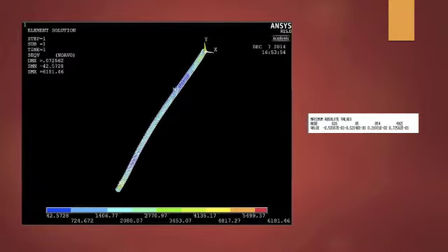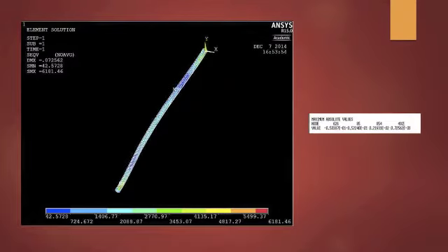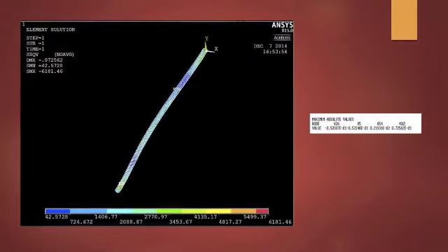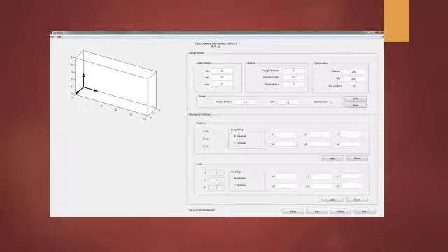One of the biggest issues of optimizing this beam is that it has a very big aspect ratio, since the diameter of the beam is so much smaller than its length. So we have issues of finding the right resolution and number of elements so that we can use the topology optimization. We downloaded software that allows us to change the number of elements used in the X, Y, and Z directions. We ran the topology optimization using a reduced aspect ratio with the intent of scaling it up later on.